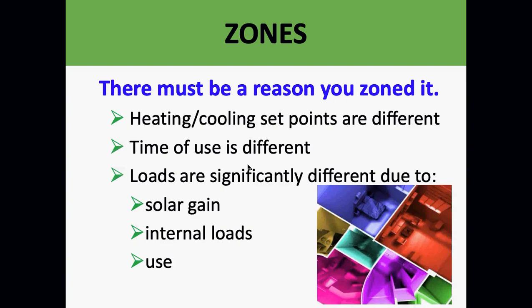But again, most often in residential construction, unless you are using ductless splits or supplemental ACs and heat, it is difficult to zone a system. Of course, if you have hot water, it's really easy. But then you lose the capability to air condition easily. So again, we need to take a look at zoning, because the newer construction, the newer buildings, the larger buildings, the commercial buildings, all are zoned.